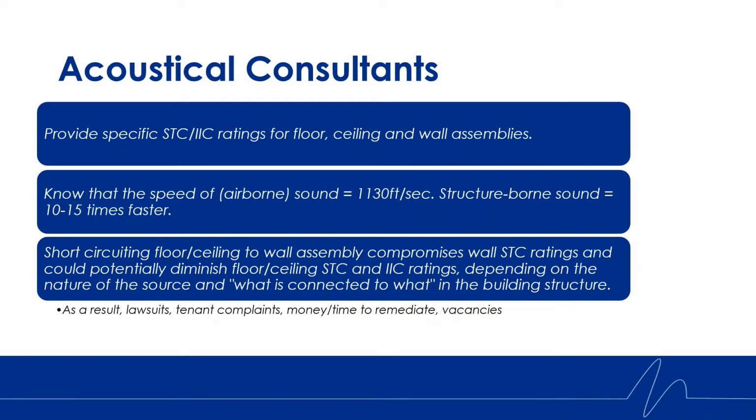Our consultants also are aware that, fun fact, the speed of airborne sound, sound traveling through air, is about 1,130 feet per second, and much harder to control is the structure-borne sound, which, depending on the construction materials in the building, whether steel or wood, etc., travels at a rate of about 10 to 15 times faster.